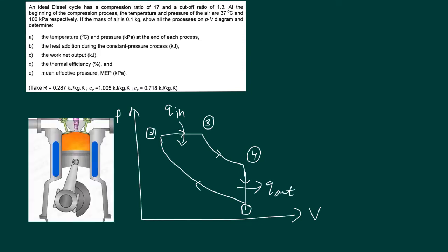If we recall from the video explanation on the diesel cycle, this heat addition here is happening at constant pressure. So you will see that this is where your combustion process takes place. As the combustion continues from the beginning up to this volume, the piston cylinder goes downwards. That's why you have the changes of volume in here, right? The combustion stops once it is fully combusted.